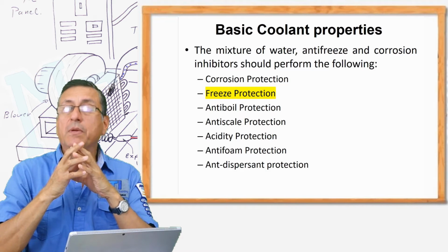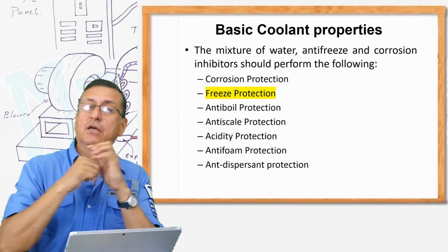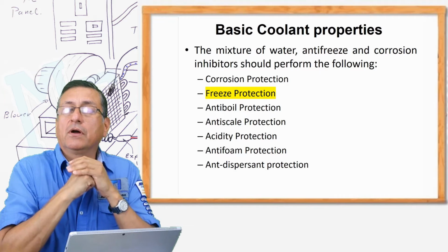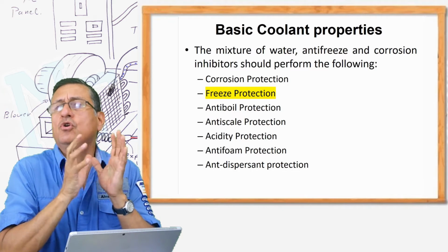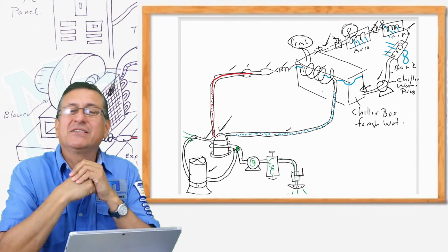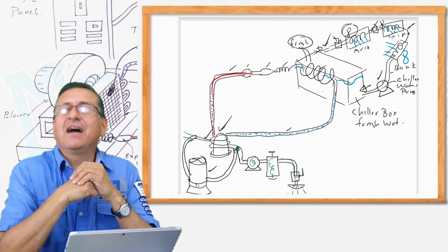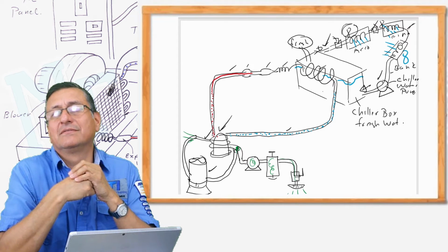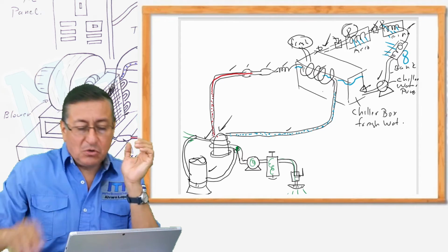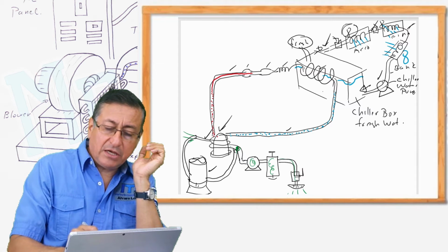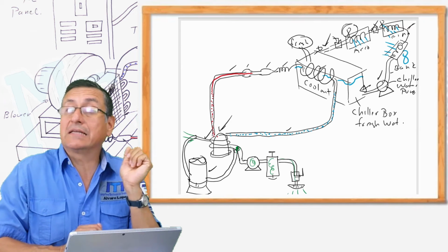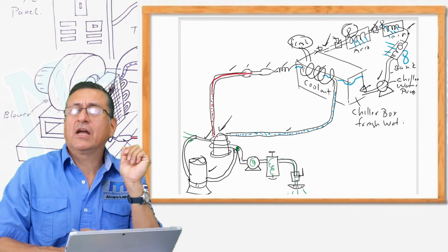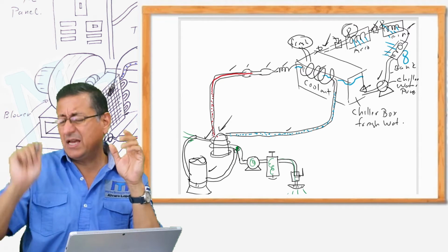For that reason, people prefer to use coolant instead of fresh water. And the coolant is not expensive; it's very cheap. I have a leak of coolant. Oh yeah, you added coolant in this container. Right now, in this container, you have coolant. It's water plus glycol. Oh, can I top it up with pure water? Yes, no problem.